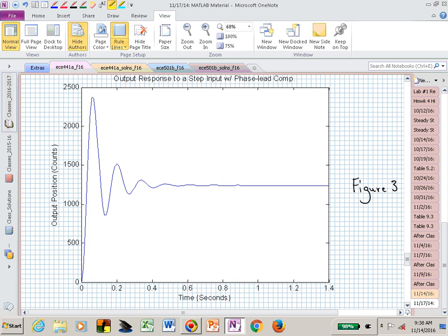You go in and you lay this on your boss's desk and she goes, "What are you doing? Are you being funny? I told you to control this system, and you made it go to 1,000 or 1,200, and I want it to go to 2,000." So you leave her office and you go back to your desk and you go PID. No, you go PID, really the I part. You want to put in an integrator to try to reduce that steady state error. That integrator is going to integrate away that error and drive your final value to lock on to where you reference it. Question?